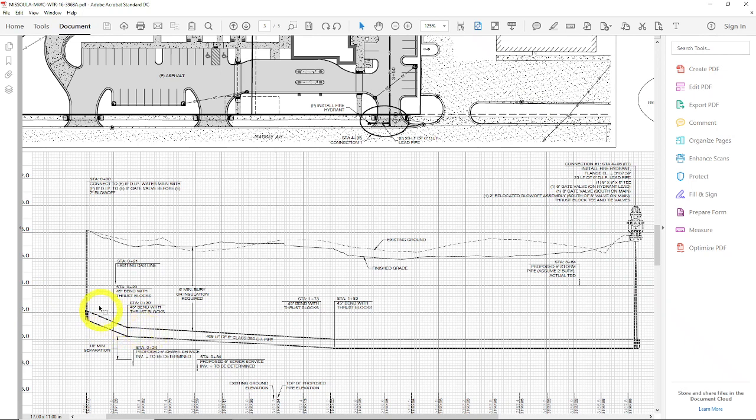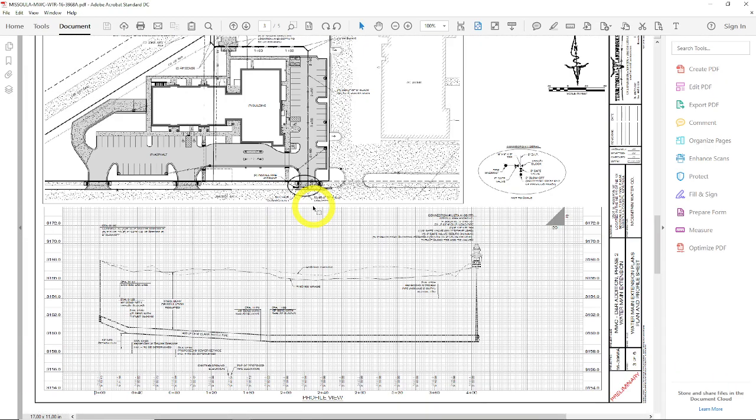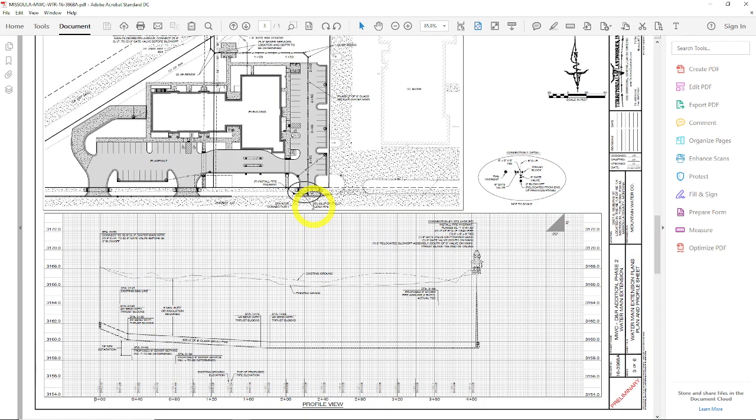and then our pipe network shows here on this profile view. This is one of the more handy things with pipe networks, the ability to superimpose them and add them to profile views, so you can do your horizontal or your top edits. You can do your vertical edits side by side on a plan profile sheet. So that's getting a little deeper into pipe networks.